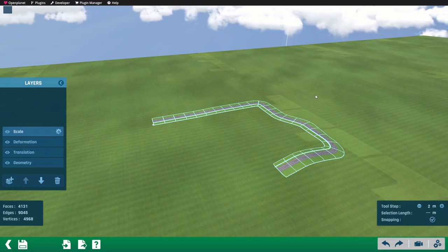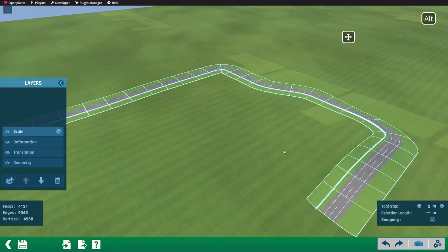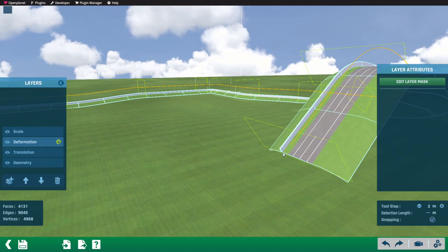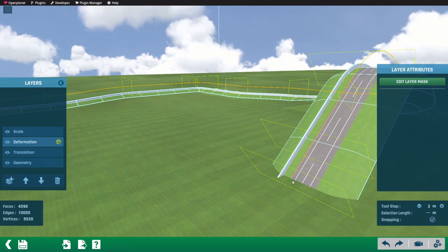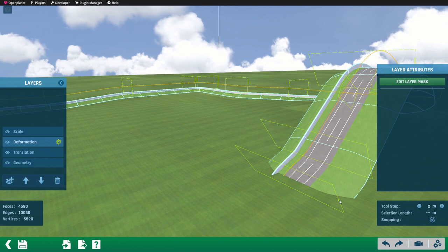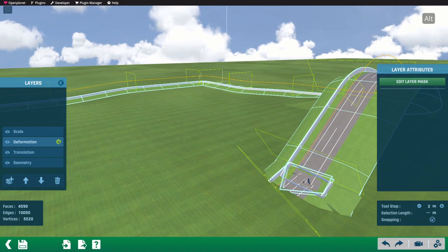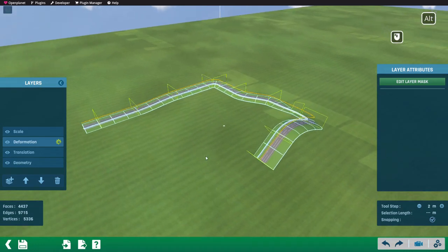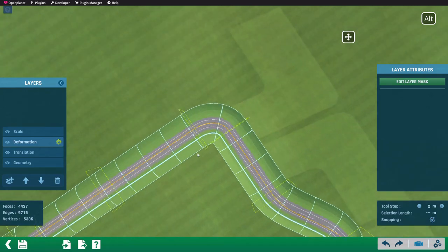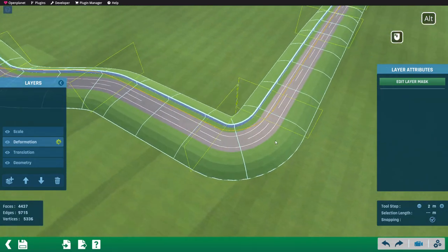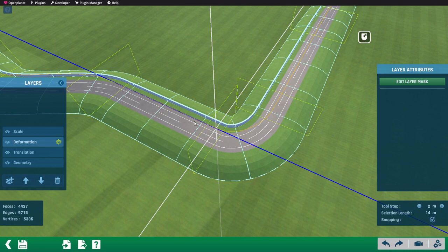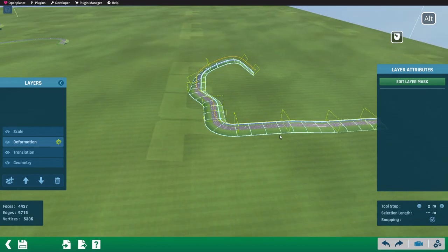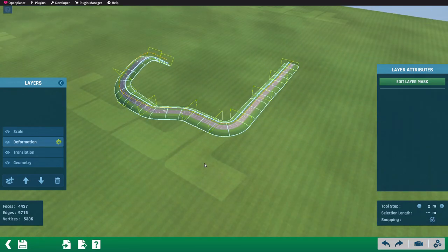Disadvantages are: one disadvantage is that small angles cannot be executed perfectly. Another potential drawback is an editor lag when the item becomes too large. This may require limiting the overall length of the track or simplifying the geometry, depending on the capabilities of the computer. Editing the deformation later can also be limited. For instance, adding a 90 degrees turn in the middle of the route will not rotate the following parts of the track by 90 degrees. While minor adjustments like widening a turn are possible, significant changes may be challenging. Finally, a complete track in one item cannot be reused for a different track. Reusability is only possible with item sets.